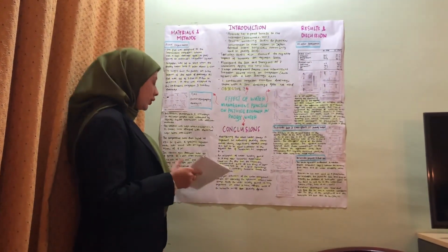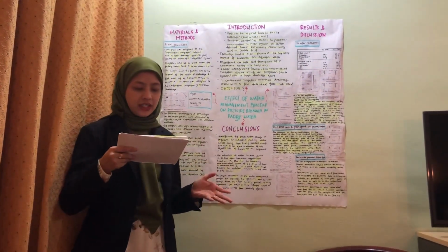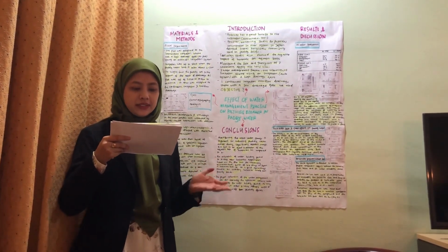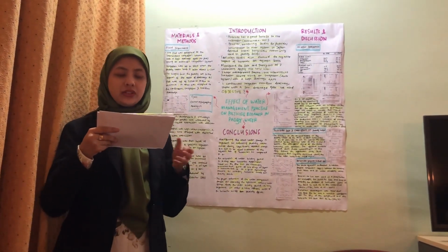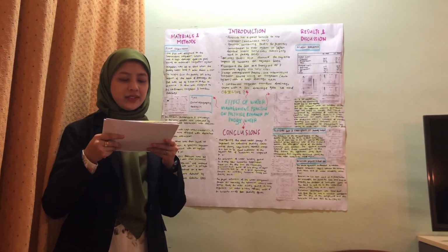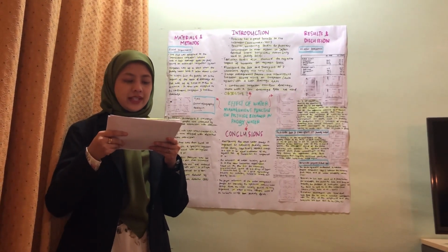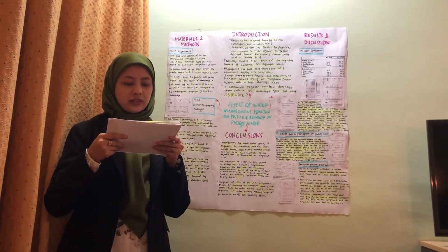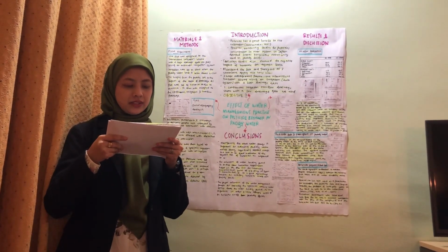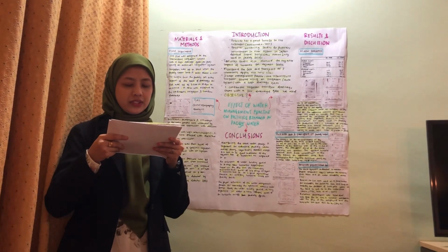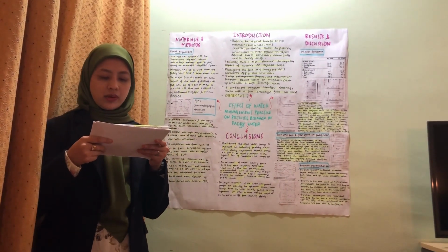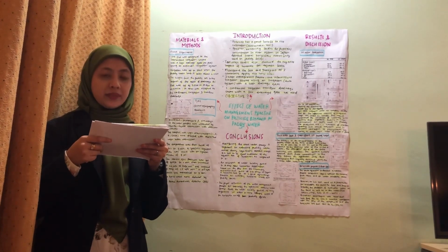Okay, lastly, the conclusion from this study: controlling paddy water runoff by the intermittent irrigation scheme using an automatic irrigation system with a high drainage gate saved irrigation water and prevented herbicide runoff, whereas the continuous irrigation and overflow scheme lost a significant amount of water as well as herbicides from the paddy field.